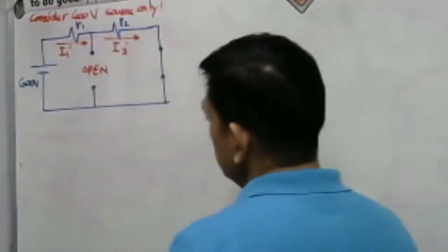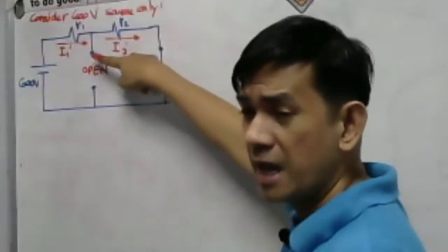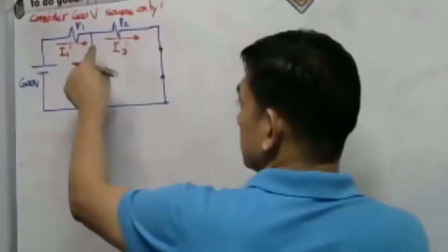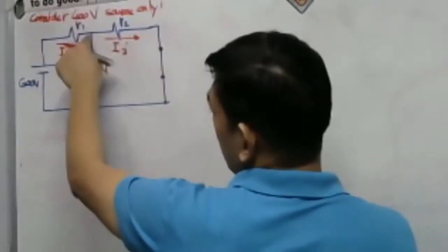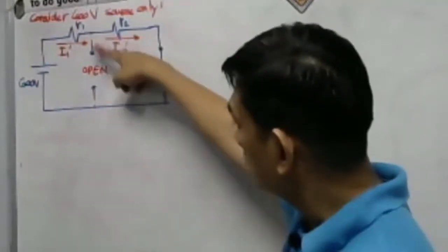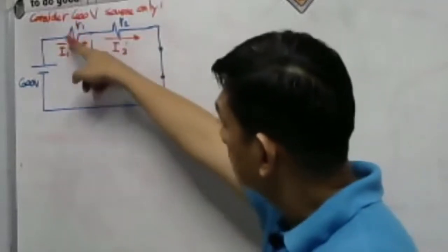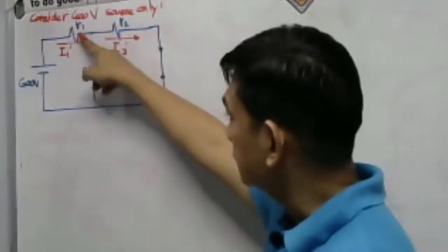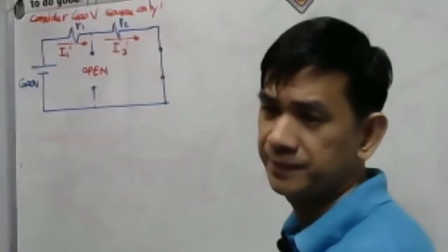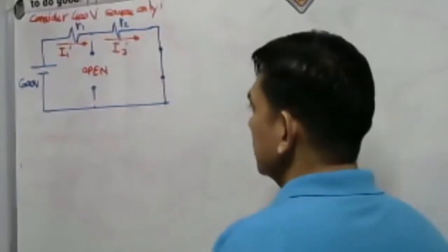And remember, this is already open circuited. This is idle now or useless. Okay? It's just like taking away this conductor. No? Tanggalin mo na lang yan. Removing this conductor. Two conductors. So we'll just be having here a circuit, a series circuit, I mean. The R1 and R2 will become series. Okay? So magsi-series na lang yan, mga kawerpa, no?